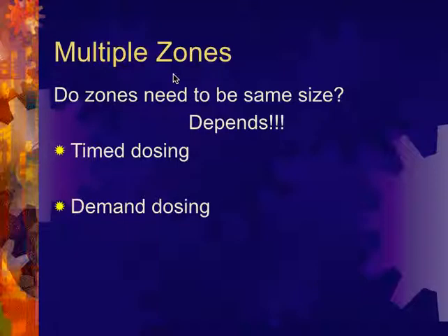The reason is because when we're time dosing, the pump is going to come on for a given amount of time. And we've already discussed that if we're time dosing and we're using the same number of emitters, the same number of doses per day, a maximum of 12, our on and off times always stay the same. It's a 10-minute on time, and it's a 2-hour off time. What regulates the actual flow during those sequences is the emitters themselves. They're pressure compensating. Once they're pressurized, each emitter will only emit 0.42 gallons an hour. So if you have more emitters in the zone, you're going to have more flow, but you're also going to have a larger drip field and more soil to absorb it. But you'll have the same amount of water being dosed into the soil proportional to the square footage.